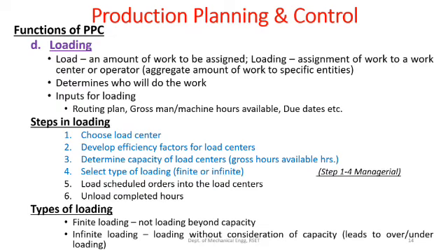Now the next function of PPC after scheduling is loading. Before going into the term loading, we will first discuss the term load. Now load is the total amount of work that needs to be assigned, or an amount or quantity of work that has to be assigned to a particular entity. That entity can be a person or a work center, okay, a place where work is happening, or it might be assigned to a particular operator. So the amount or quantity of work that needs to be assigned is called load, and the process of assigning work to a work center or an operator is called loading.